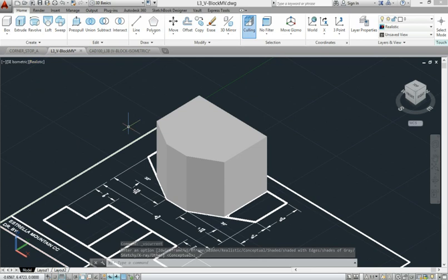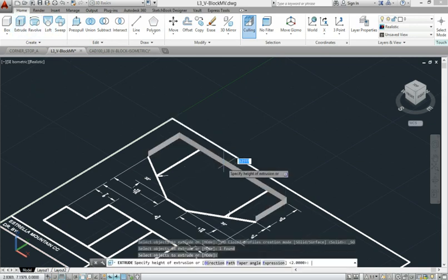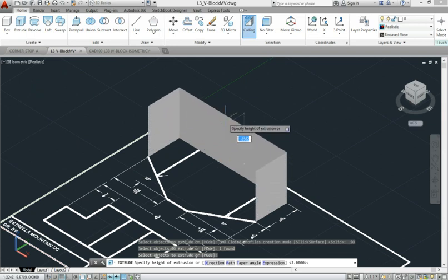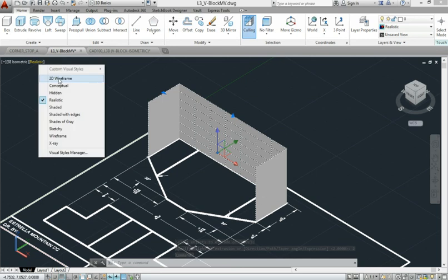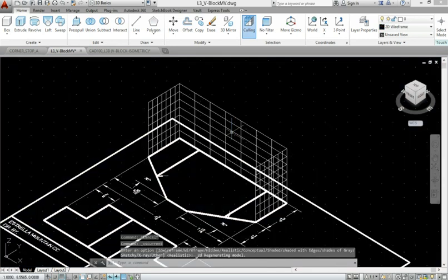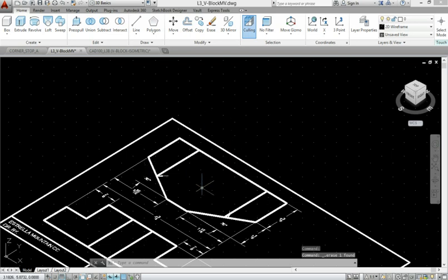Now if you try and extrude and this box does not appear, I'll explain why. Let me delete this. Let me pick extrude. Let me pick what I think is a boundary. Hit enter, and I pull up and I get a thin feature. This is not the same thing. This is considered a wireframe, and unfortunately it's not what we want. So if you create something that's not supposed to be there, as this wireframe, just delete and repeat the steps.